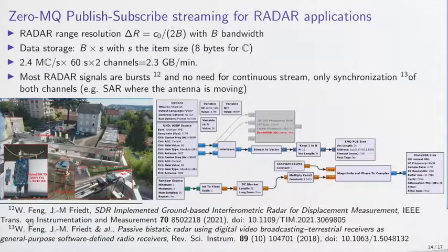In this example, we use either a Wi-Fi dongle or a Pluto SDR as a pseudo-random signal source, and this pseudo-random signal source is recorded by a B210. The B210 Ettus Research software-defined radio is a dual-channel coherent receiver. One of the outputs of a random source, whether the Pluto SDR or the Wi-Fi dongle, is recorded by one channel of the B210, and the second channel will record whatever is collected by an antenna.